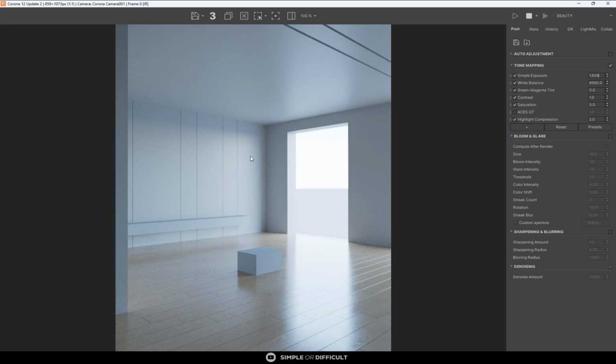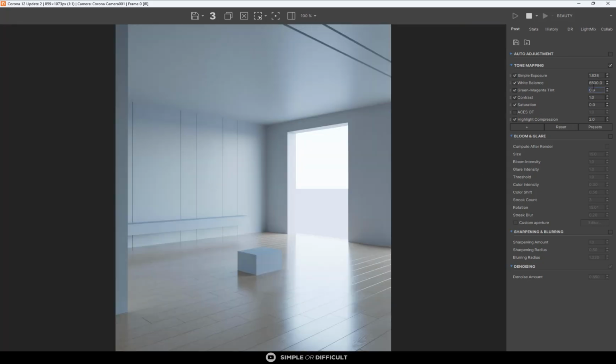And because we don't have windows in here, it is part of what is making the entire thing too bright. But I want to show you this floor slab, this floorboard that we have here. So I'm going to reduce this a little bit and then add this and then reduce it to 0.2, thereabouts. So you can see the floor already being glossy.